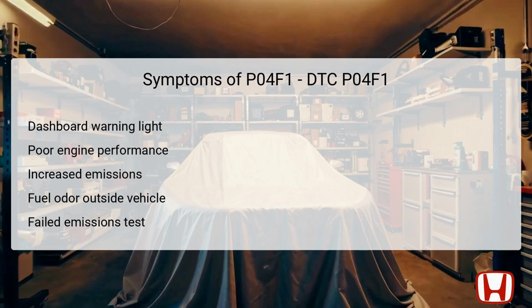Increased emissions are another concerning symptom, which not only affects the vehicle's ecological footprint, but can also lead to failing an emissions test. Additionally, an impacted EVAP system may lead to a fuel odor outside the vehicle, particularly after refueling. These symptoms highlight the urgency of addressing the underlying problems indicated by the P04F1 code.